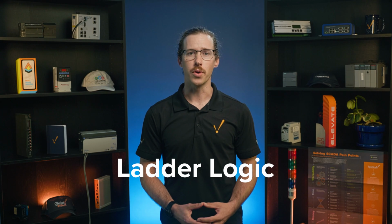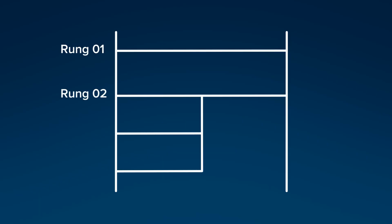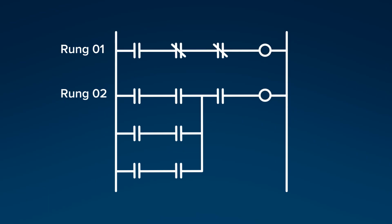Ladder logic, known as ladder diagram, is a graphical PLC programming language based on relay logic's circuit diagrams. Ladder logic consists of 2 parallel bars connected by a series of rungs assembling a ladder, hence the name. There are contacts and coils on these rungs, which symbolize inputs, such as sensor value, and outputs, like a motor run command. The vast majority of control system programming in North America uses ladder logic, and for good reason. It's flexible, versatile, simple to troubleshoot, and easy to learn.